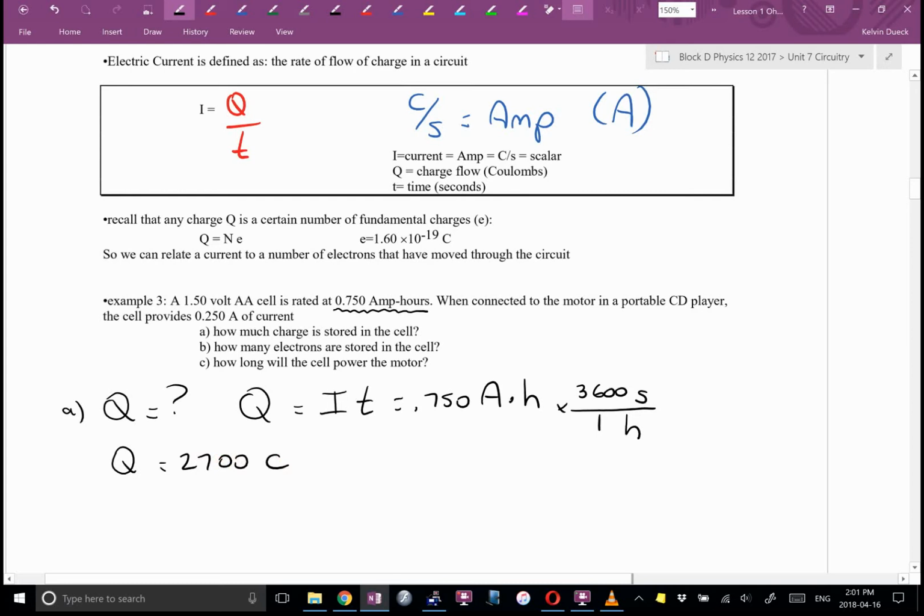Now, you remember I said, so where's my AA battery? Here's a AA battery. I said 1 coulomb is enough to kill you. Technically, this has more than enough charge to be fatal. It's just there's no way you could get the charge out of here so fast for it to be fatal. It's a chemical reaction that's doing the work to separate the charges to make them available, and that chemical reaction is not very fast. You could safely put this in your mouth. I'm not going to because it's disgustingly dirty, but putting it in my mouth probably would complete the circuit, and I doubt I'd even feel it.